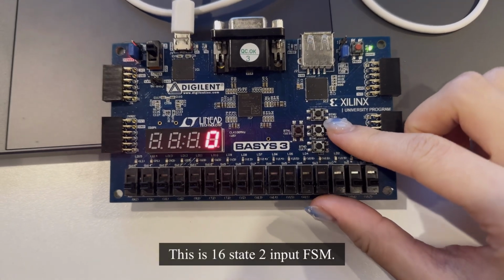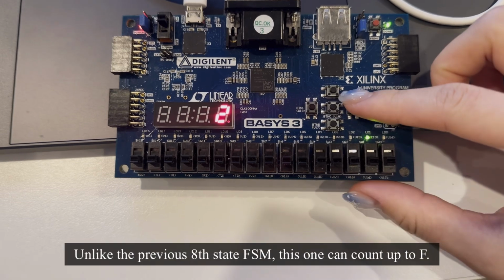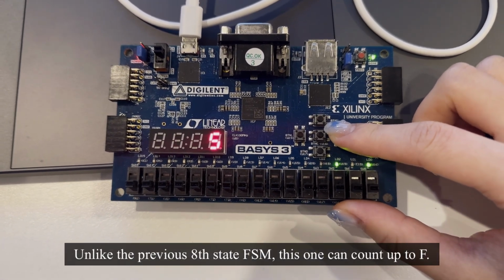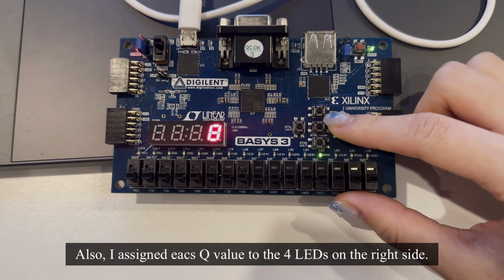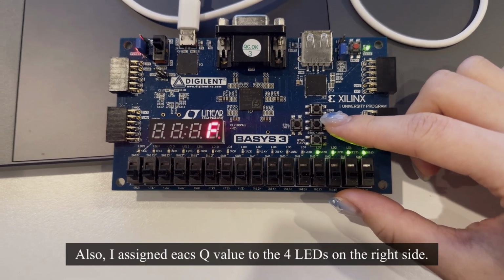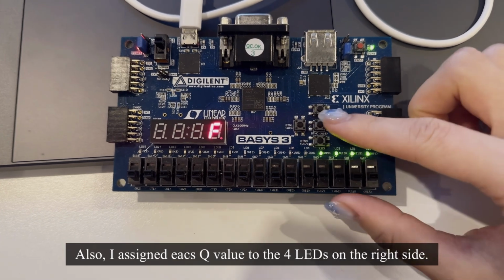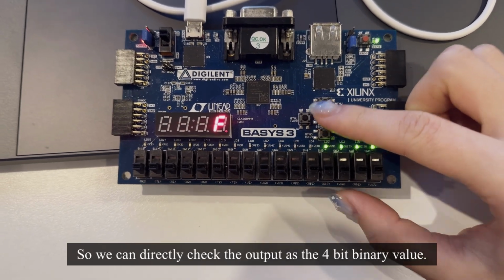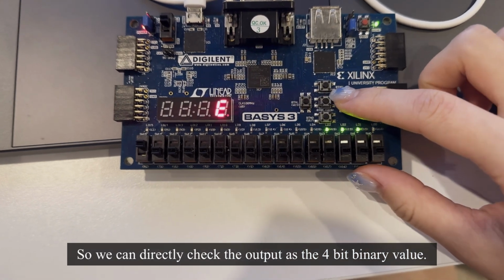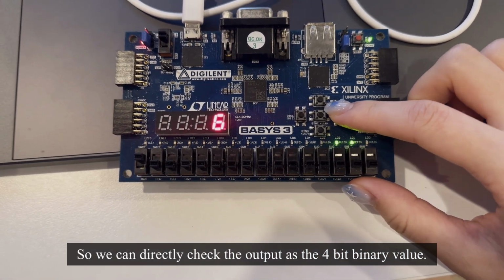This is the 16-state 2-input FSM. Unlike the previous 8-state FSM, this one can count up to F. Also, I assigned each Q value to the 4 LEDs on the right side, so we can directly check the output as a 4-bit binary value.